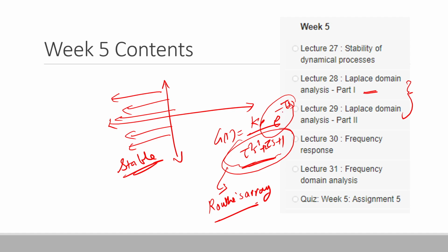So there are approximation techniques whereby we can approximate this using a linear term, but those are only approximation techniques. So in the presence of this exponential term, how can we analyze the response of the system? We can do that by converting the system into frequency response. Basically we just replace s equal to jω, and on the basis of the plots of ω we will come upon a different kind of stability criteria, that is the Bode stability criteria.